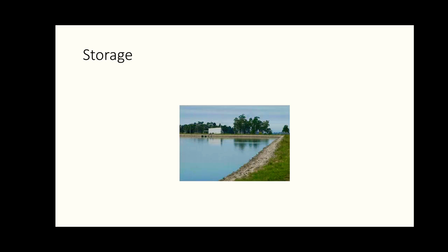So storage irrigation schemes are comparatively of bigger magnitude, because they involve much more expenditure than direct irrigation schemes, since water is to be stored and then taken off. One or two main canals take off from a reservoir. Due to formation of reservoirs, some land property may be submerged upstream of the dam. The network of canal system conveys water to the agricultural fields through various regulatory works, cross drainage works, aqueducts and siphon passages, canal siphons. These are all required. The cross canals too.